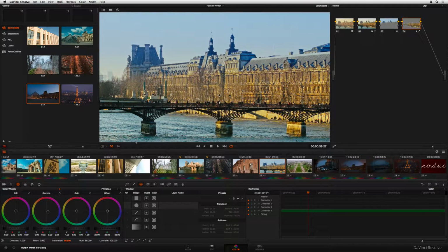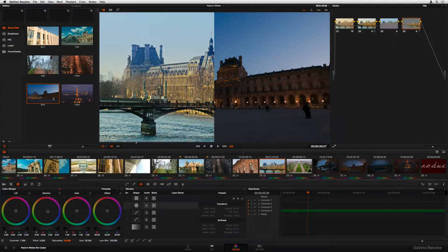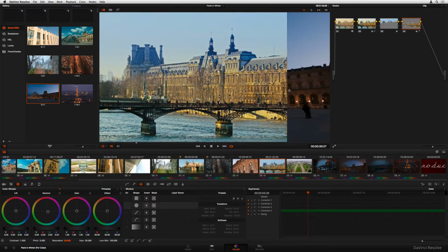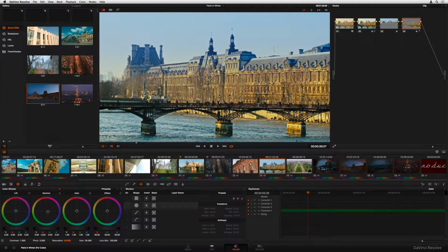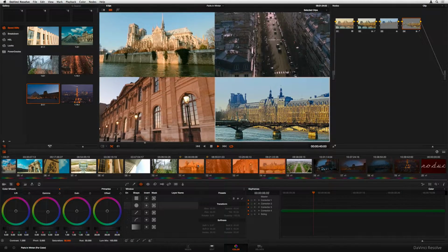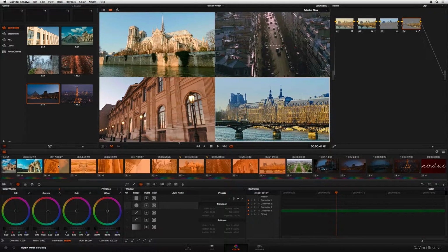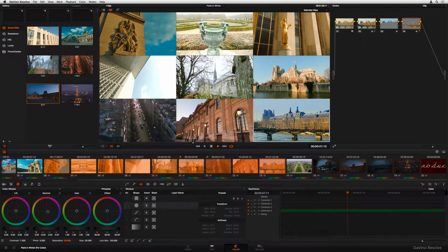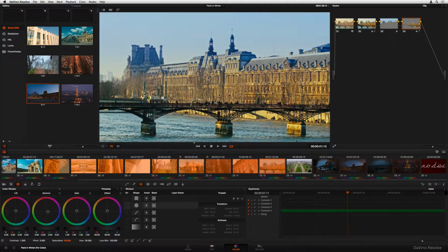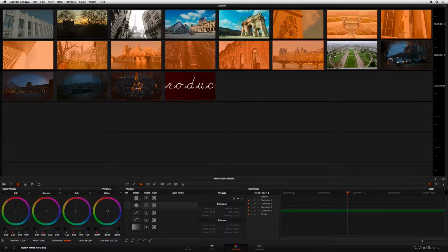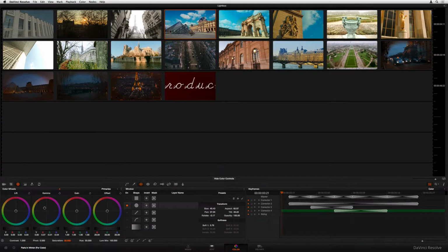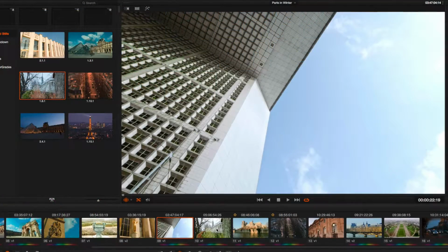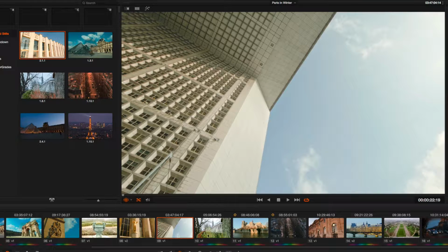When matching clips together for a seamless grade, a complete set of comparison tools makes it easy to compare different clips, whether you're using a wipe to compare a saved still from the gallery, using Resolve's incredibly flexible split-screen view to compare multiple selected clips in the timeline, complete with playback, or using Resolve's Lightbox view to compare every single clip in your project. While you work, you can copy grades to speed up your workflow, copying saved grades from the gallery, or copying from other clips in a variety of ways.